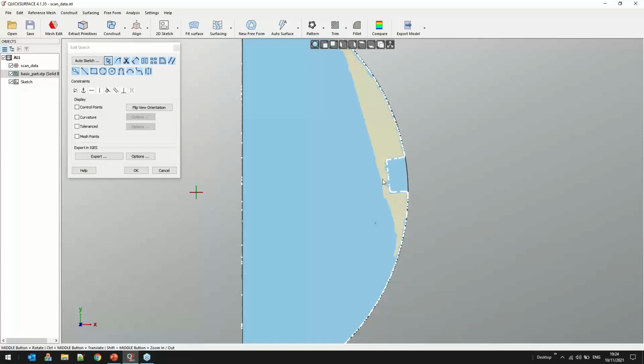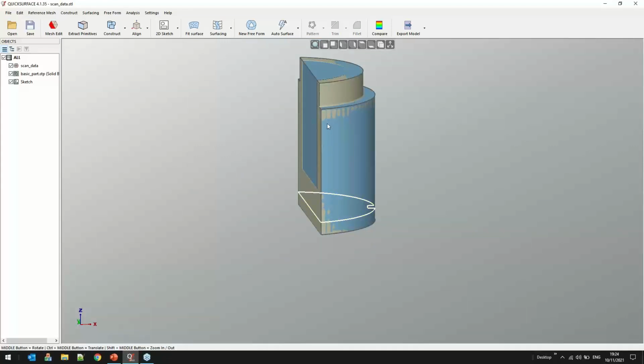But because these points here, for example, don't exist in the original cut model, they will be taken into account. So it's not a good idea. Fine align will try to move everything and balance the minimum error, and you will not actually get what you need. So if you have a roughly aligned object like this one, I'll delete the sketch, I don't need it anymore. It's recommended that you use smaller values, for example 0.5 millimeters, and then you run the software.